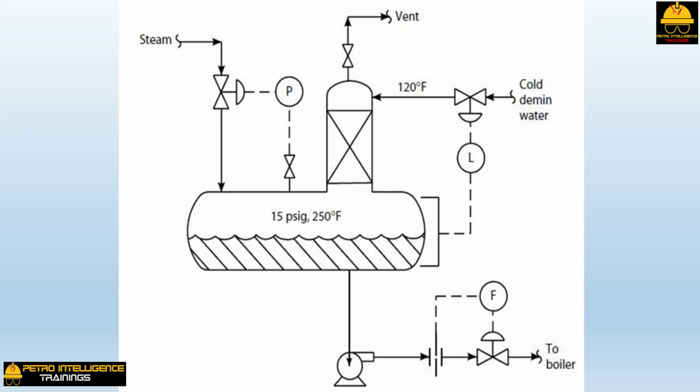In the event that there is too much residual oxygen in the deaerator effluent, the flow of vented steam from the top of the deaerator should be opened. However, often there is no vent valve, but just a fixed orifice vent. Or perhaps the supply steam control valve is 100% open.